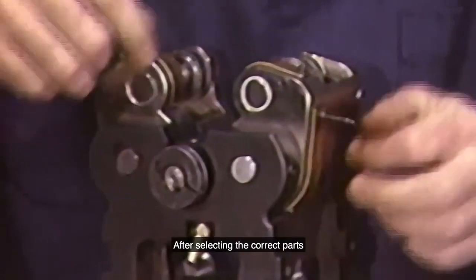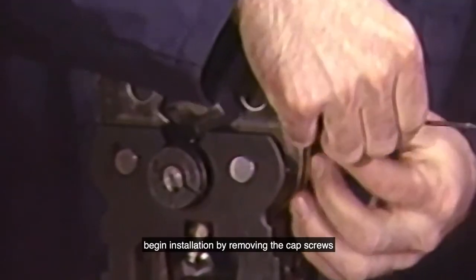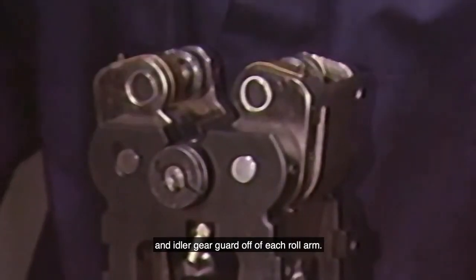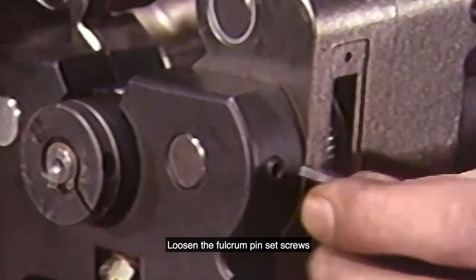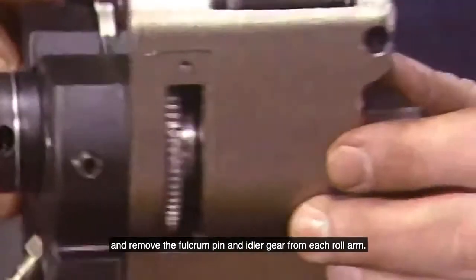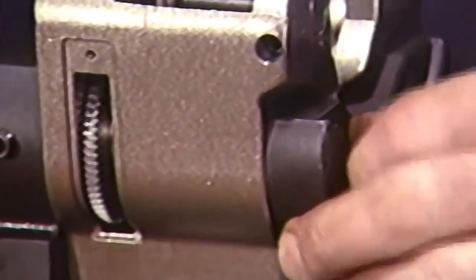After selecting the correct parts, begin installation by removing the cap screws and idler gear guard off of each roll arm. Loosen the fulcrum pin set screws and remove the fulcrum pin and idler gear from each roll arm.